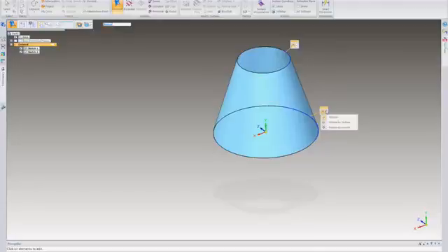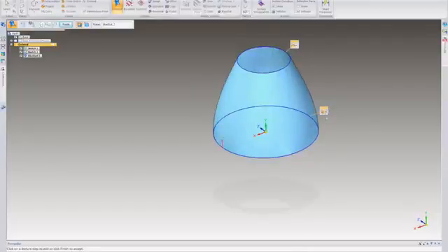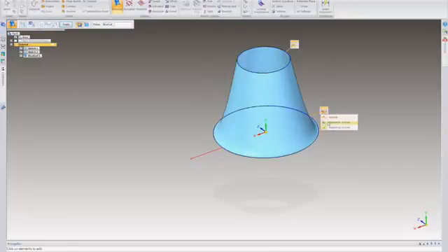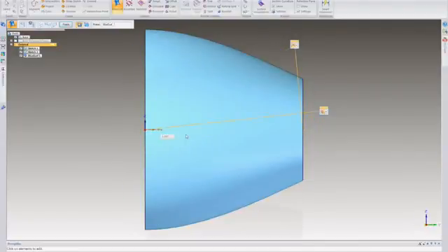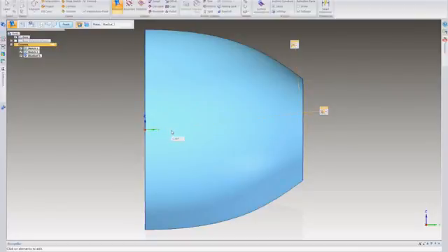And again, of course, we get our different types of control. This one has more than the previous one. So this has normal, and of course the bottom one would be parallel to section. And of course your control is designated by this little control point here. So the more it's pulled in and out, if I go to the side view here, and as I drag this, you notice it's changing the magnitude of the curve of my geometry just by using this control point.